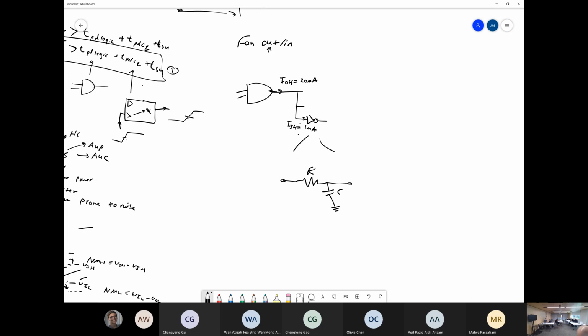So you'd have capacitive loading from these gates, and you'd have the finite output resistance of the logic driver, right? So inside here, you either have a resistor tying the power supply to the output, or a resistor tying the ground to the output. So it's like having a switch, right? I can either switch in a resistor to the power supply or switch in a resistor to ground.